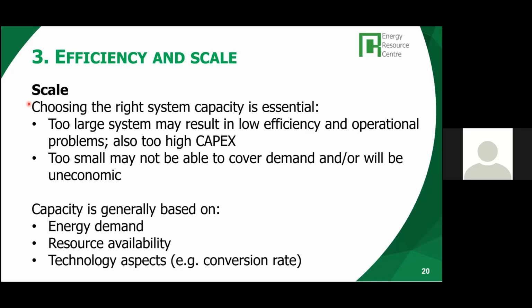So that means that choosing a better scale can actually have benefits in terms of conversion efficiency, and from the same amount of biomass feedstock, you could produce more energy if you have the appropriate scale. And also some systems, particularly gasifier systems, but also boilers, can have operational problems when they are run at a very low loading rate.